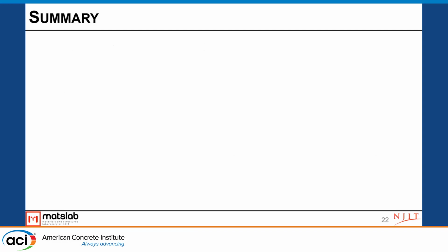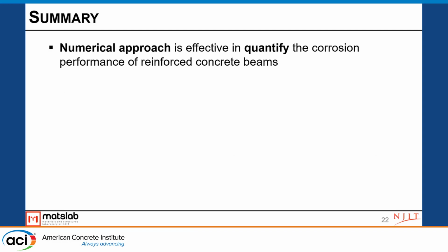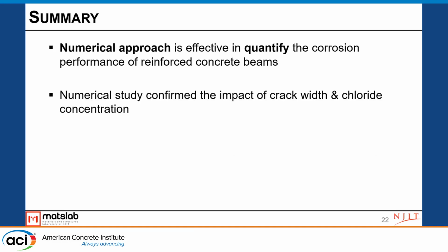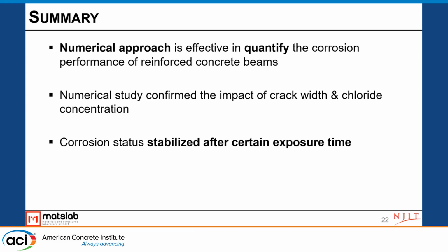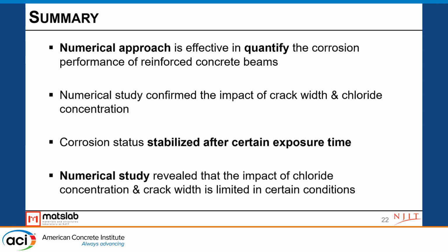And here's the summary. This numerical approach is very effective in quantifying the corrosion performance. Through this numerical simulation, it confirmed the impact of crack width and surface chloride concentration, and that the corrosion started to stabilize at a certain time.